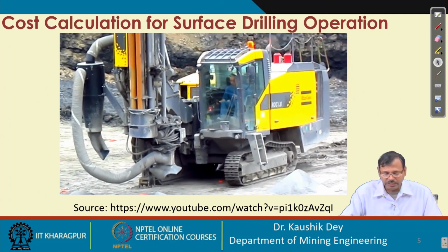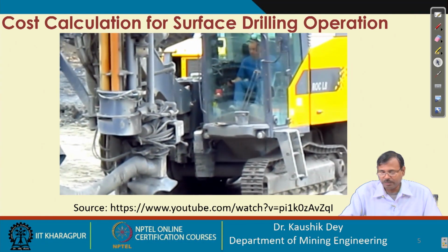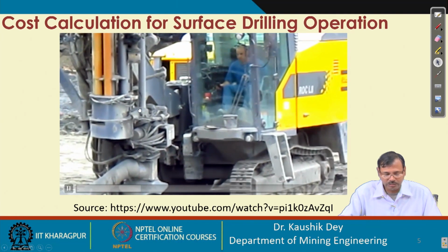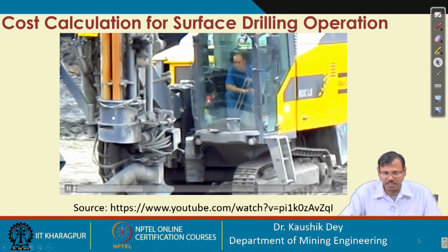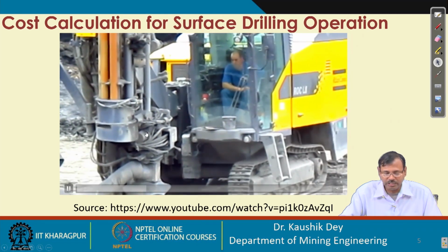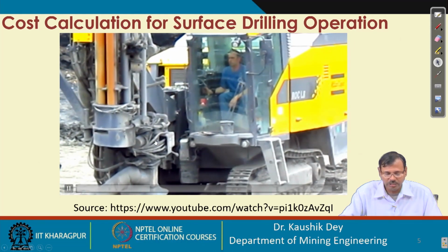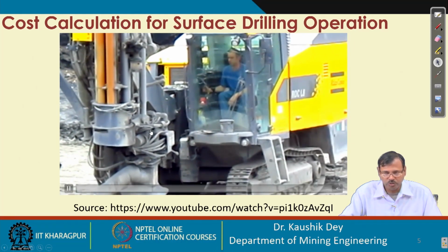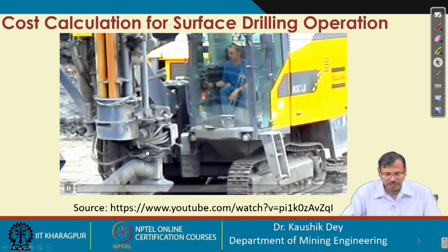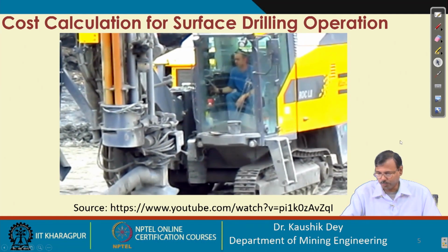So, this moving is basically an unsafe act. Logically, whenever the machine has to move from one place to another, this drill rig or drill must be in the horizontal position, not in the vertical position. But here, as it is moving a very small distance, the operator is not doing that. It is allowing the move on the mast keeping the vertical condition only. Okay, now the second hole drilling will be carried out in this place.